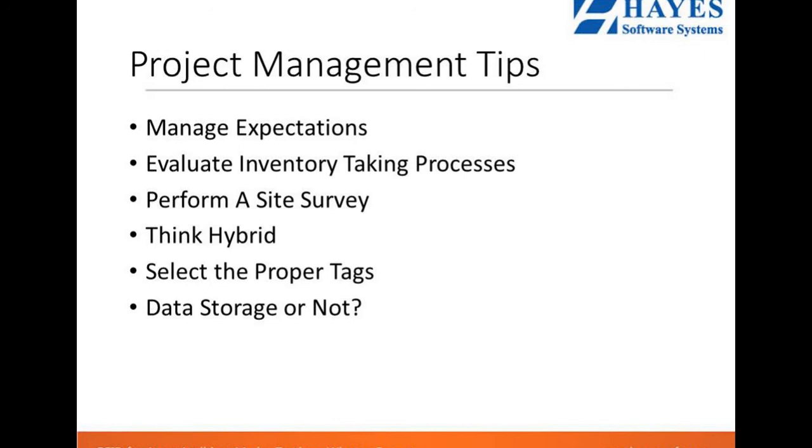Most inventory applications will simply use the RFID tag as a unique license plate that can be referenced to a database. Since most system users will have access to this application to either identify or update information about the tagged items, this method provides a virtually unlimited number of data fields for information that can be stored and accessed about that tag, restricted only by your database's limitations. Limiting access to your database through normal network security features means that as long as your database is secure, someone unauthorized who reads an RFID tag is left only with a random 96-bit number instead of any useful information.